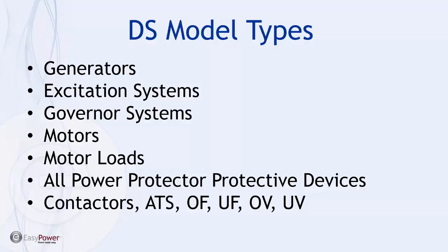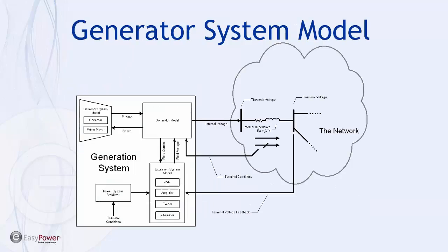And then we're adding the models of the transfer switches, and the over voltage, under voltage, over current, over frequency, and under frequency relay responses, which don't necessarily show up in the short circuit studies. So here's how it all's connected together.